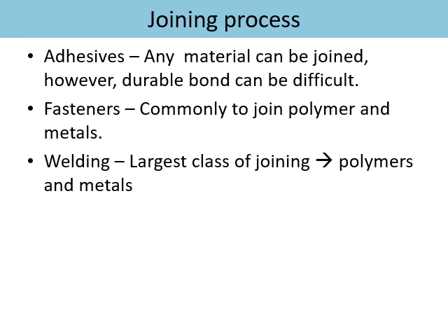We can see that each of the joining classes has pros and cons. The adhesive can be used to join both similar and dissimilar materials. Nevertheless, the bonding durability is quite low. For example, joining two wood panels with acrylic-based adhesive is better than joining metal sheets using similar adhesive. This is due to the metal surface being generally smooth and stresses are concentrated at the bonding interface.